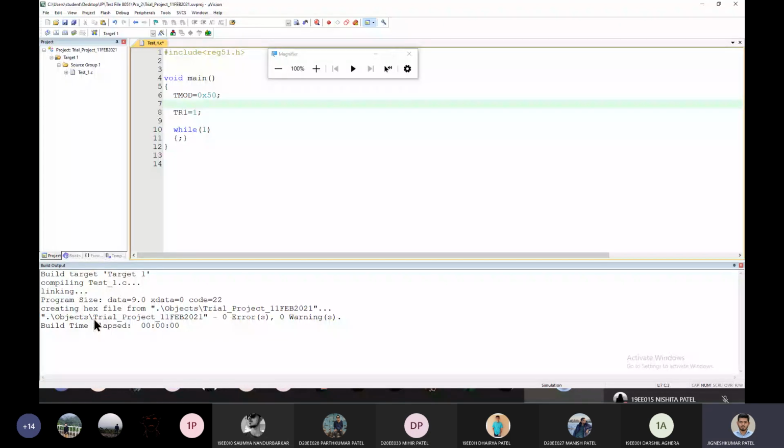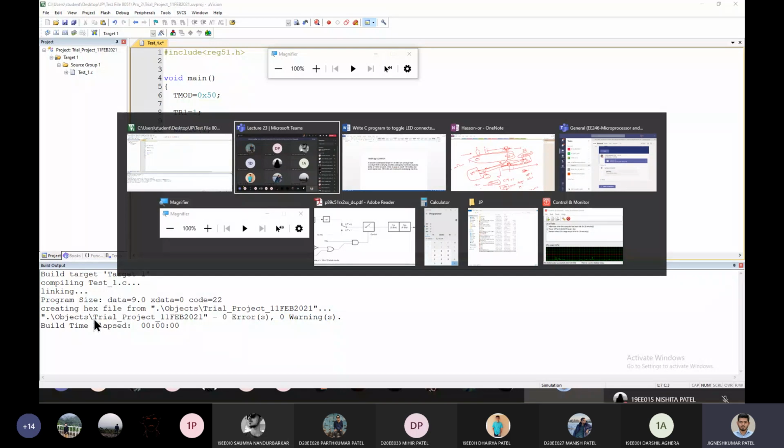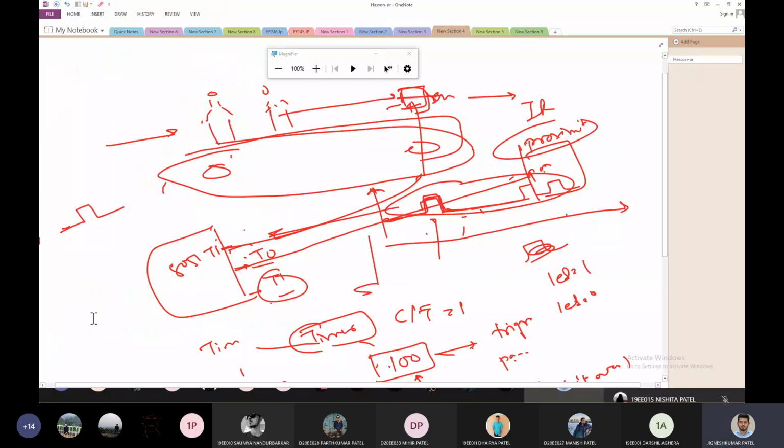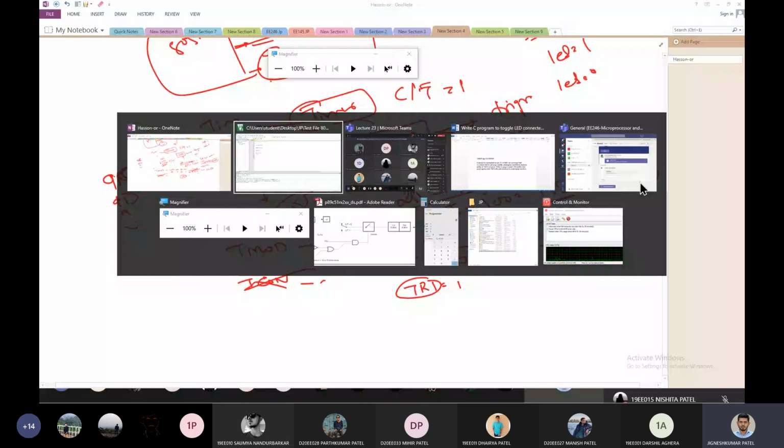Okay, so this is how we run the timer. Now the thing is that we are receiving the pulses from this bottle and we have to count the 100 bottles. So again that same principle comes here. If I want to reach the 10th step and you have allowed only 5 step moves, you have to start from the 5th or 6th step, then on your final step you will reach the 10th. Same way here we have applied the same logic and calculated a number, that is 9b, to be loaded in your timer register.